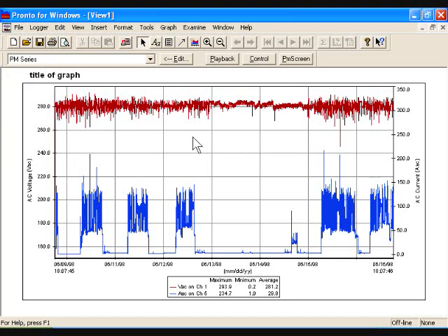Now, another thing we would want to consider is a customer's typical question: well, how long is this graph? Remember, if you touch the line, it tells you the max, min, and average, and so on of the graph. However, what we want to do at this point is left click once on this line, and it puts what we call handles, these little colored boxes, on the line.